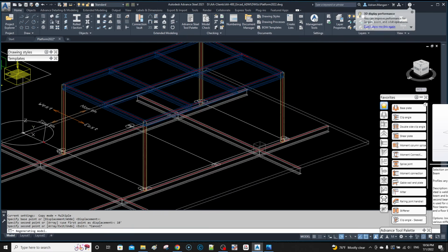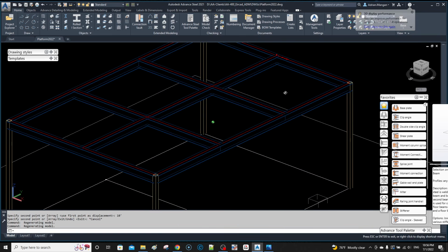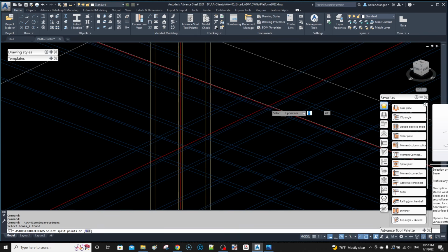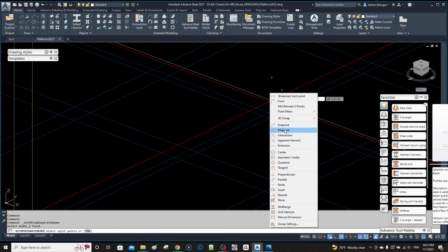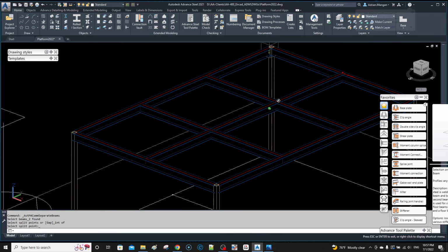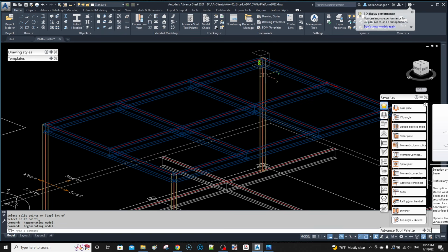Alright. So now which beams are going to be continuous and which ones? I guess a lot of people would like to make the long one. We could do the short one as continuous. So I guess generally we'll do these ones. It's stronger the other way probably because, yeah, obviously a shorter span. But let's just do this and we'll do intersection. We'll split them this way. So you can split, doesn't matter what way we split them. Doesn't really matter what size these beams are. I'm not going to get into small beams because then it gets a little bit annoying.